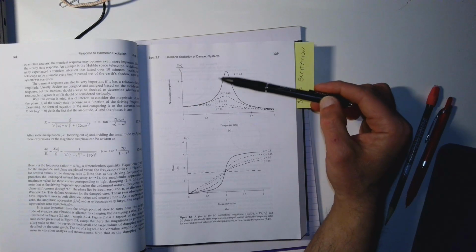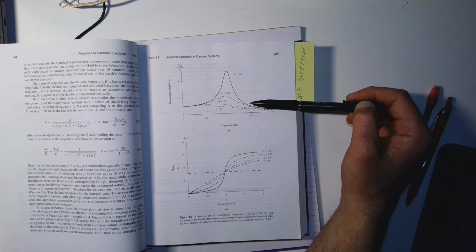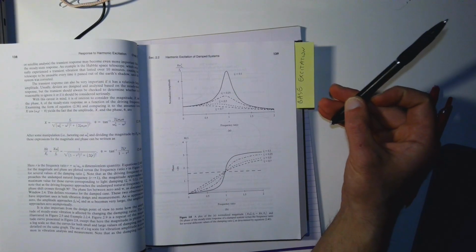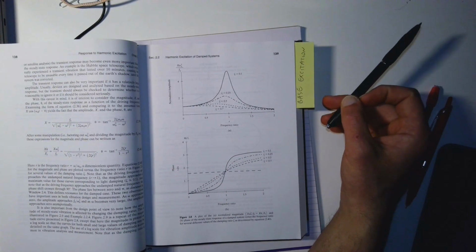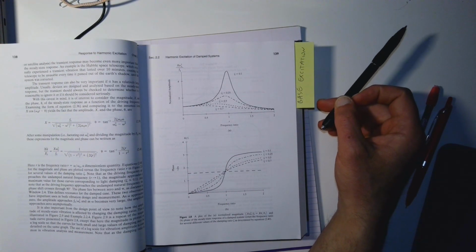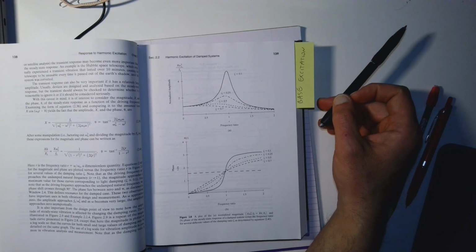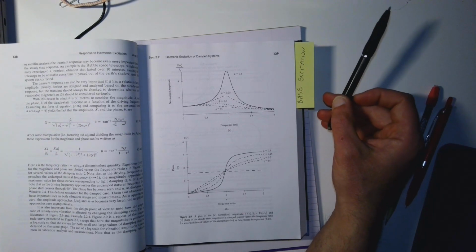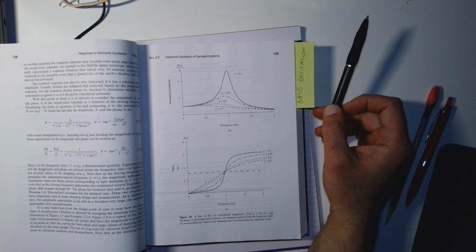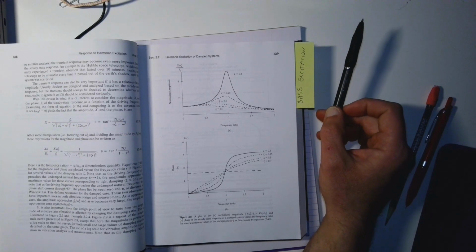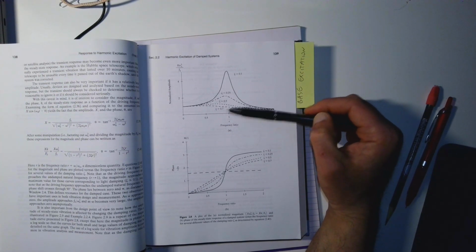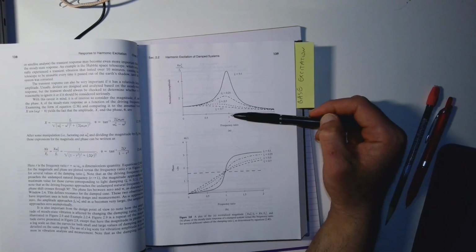Because if we have a sudden increase of the amplitude of vibration, it means that we have a sudden increase of the strain. If the strain becomes too big, we can go to plastic deformation. Again, for structural purposes, we always don't want plastic deformation. But even more than that, we can have a complete failure and collapse of the entire structure. So we always want to stay very far away from this value of r.